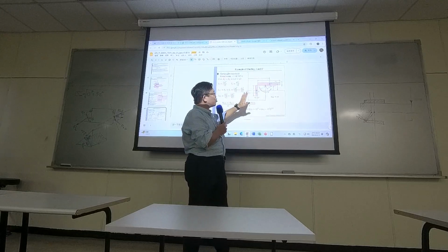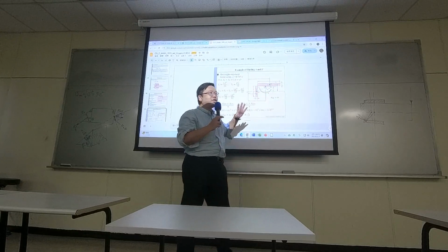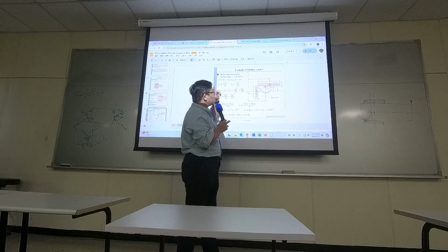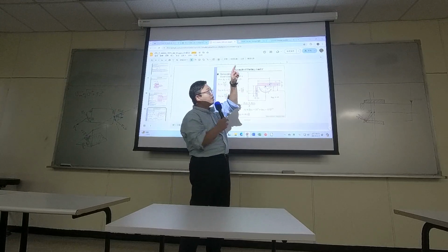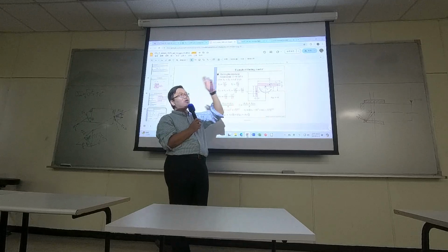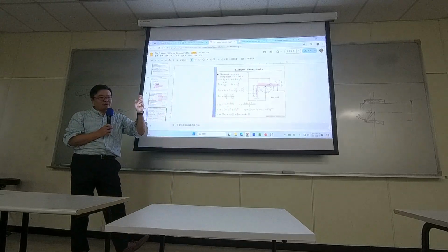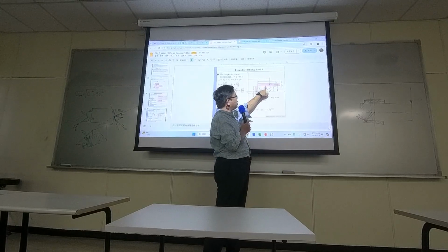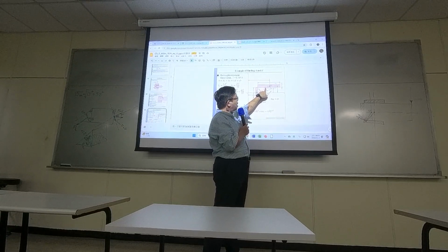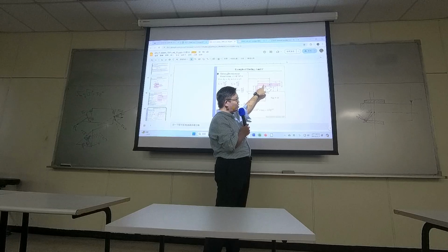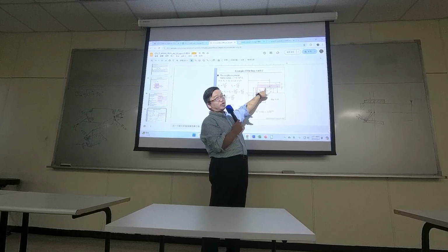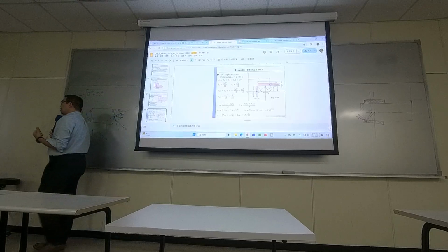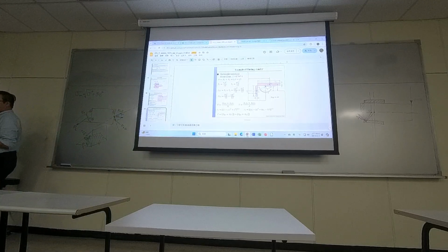Now we are treating the whole thing as the complete area for carrying the shearing stress. So we need to compute the overall area moment of inertia for the entire geometry. That's why we need to study the area moment of inertia right at the G point, and why we need the parallel axis theorem. I will do that next time.